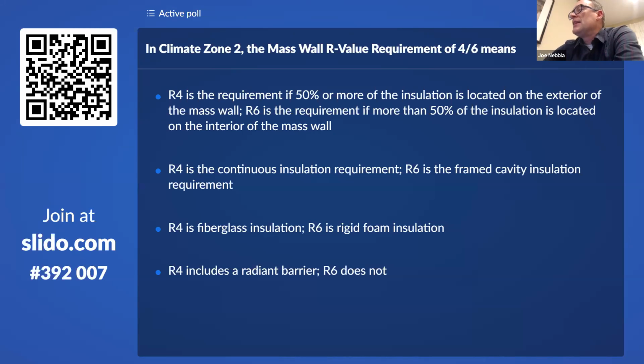Yeah, so that's always one of the hardest things to calculate. Typically you're trying to meet the R value, right? It doesn't change that R49 in climate zone 2 that you would need. So that's in an unvented attic. You're doing the roof line and you're insulating there. So you need an R49.